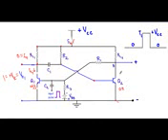As the transistor Q2 is in on state, therefore its collector and emitter terminal will get shorted, and we are taking the output across this terminal and this terminal. So our output voltage V out will be equal to 0 volt, and this is equal to logic 0, and this 0 volt is the stable state of the transistor Q2 for this circuit.